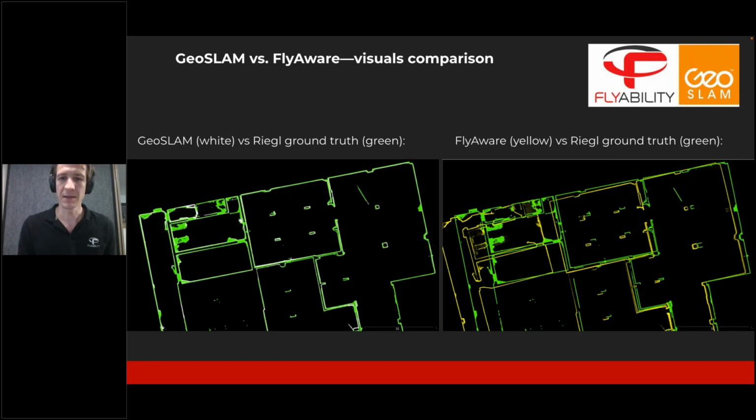So again, when you have long distances to travel, and the georeferencing and the accuracy of the 3D model you want to extract really matters, you can get a significant improvement by going with the GeoSLAM post-processing after your flights. That's the rough explanation.